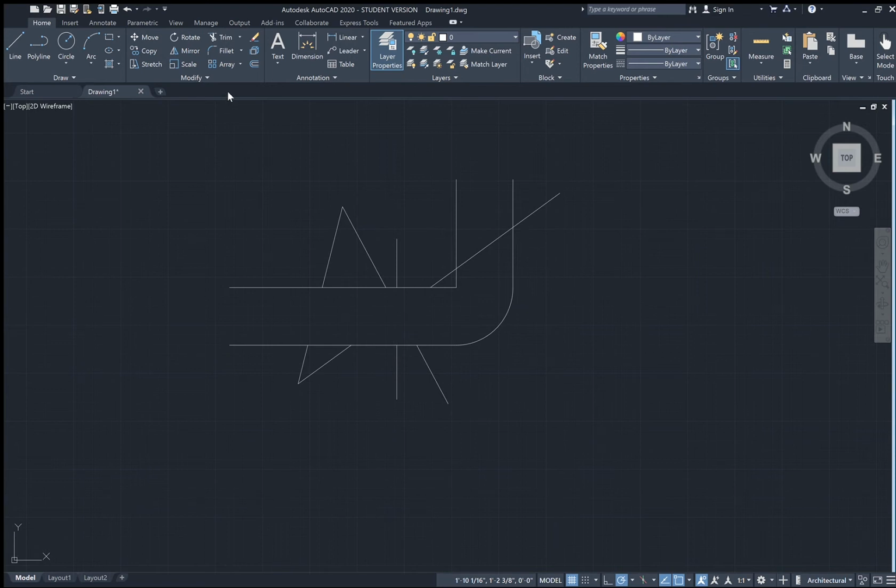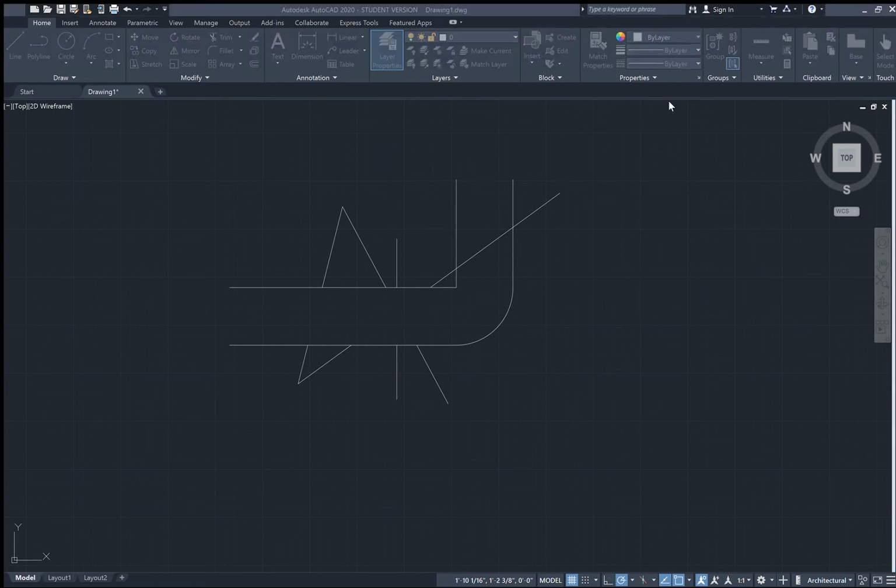And for apples, let's select line type. So this is the different types of lines. As you can see here, a whole selection to choose from. And all of these presets will be available to you as you install AutoCAD on your computer. It comes preset with all of these different lines. So you should look like this typically.